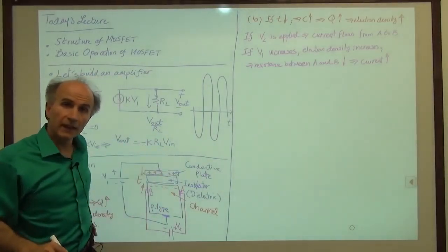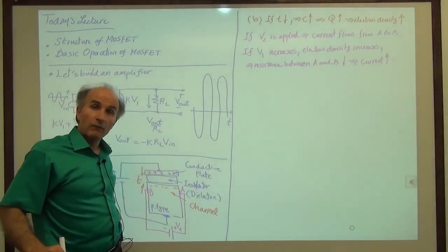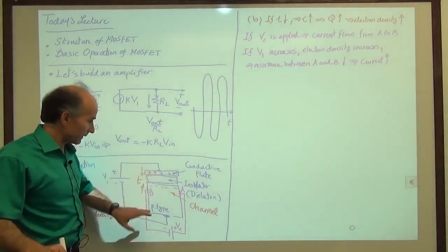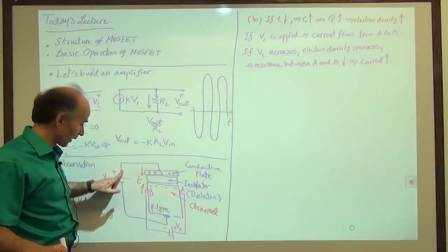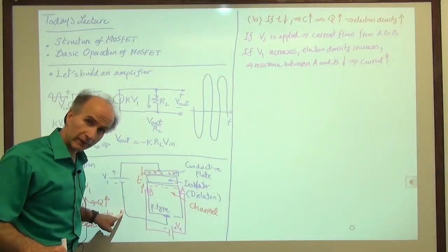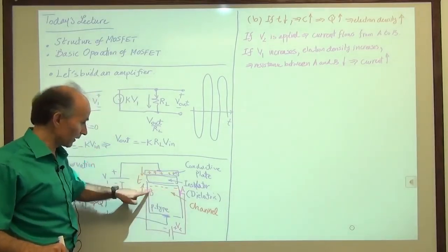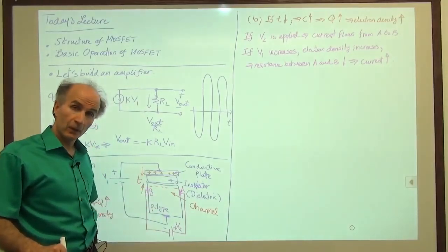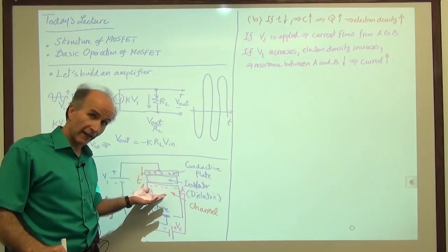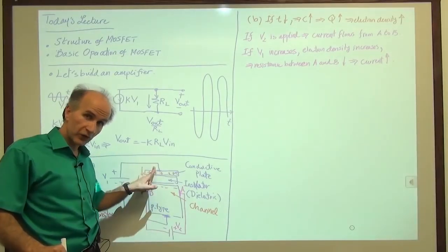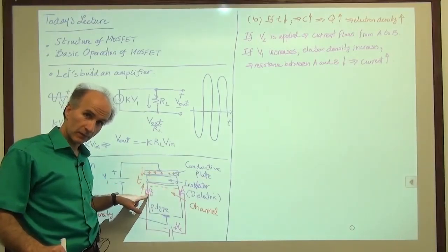So what's interesting is that a voltage connected between this plate and this plate, V1, can control the current that flows from here to here, or the electrons that go from here to here. So it seems that we have something close to a voltage-dependent current source, right?